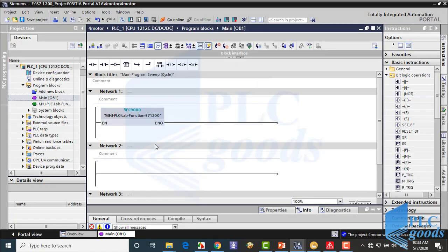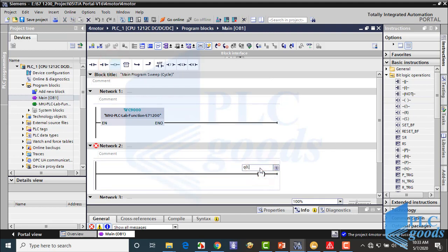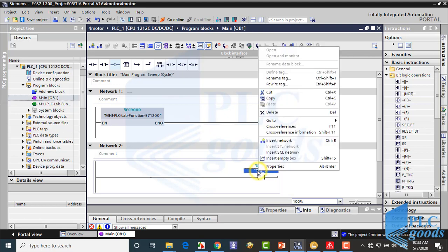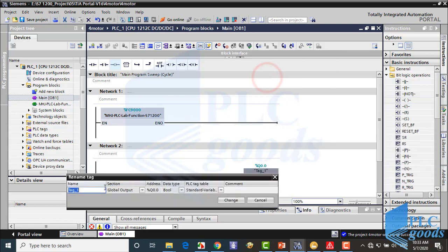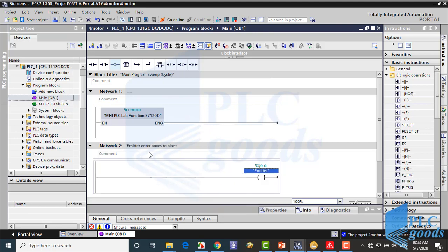Let's start to write a program in ladder language. As you know, we need this block to use Factory I/O beside our virtual PLC. Now let's insert 4 assignments respectively for outputs. By default, in every network, comments of the first output appear here.